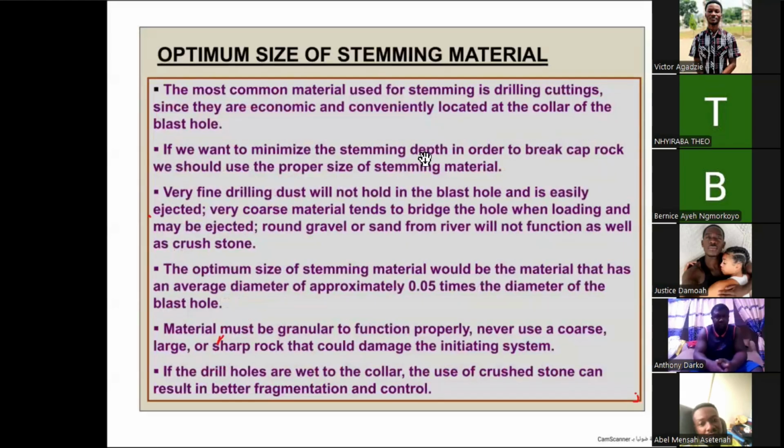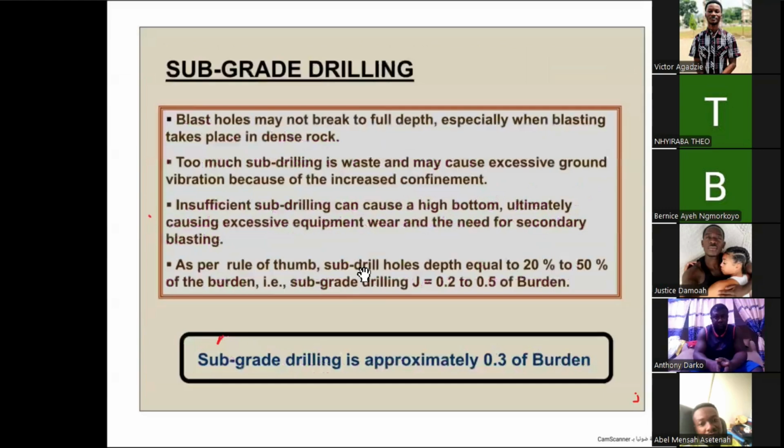We have spoken about the stemming materials already, so you can proceed with that. Subgrade drilling, that's the subdrill that I was talking about. So the subgrade we are saying is approximately 0.3 of the burden. Okay, 0.3 of the burden that you use. That is the subdrill or the subgrade.